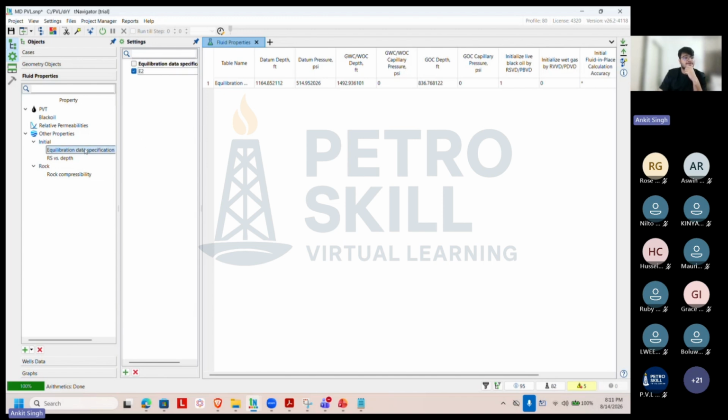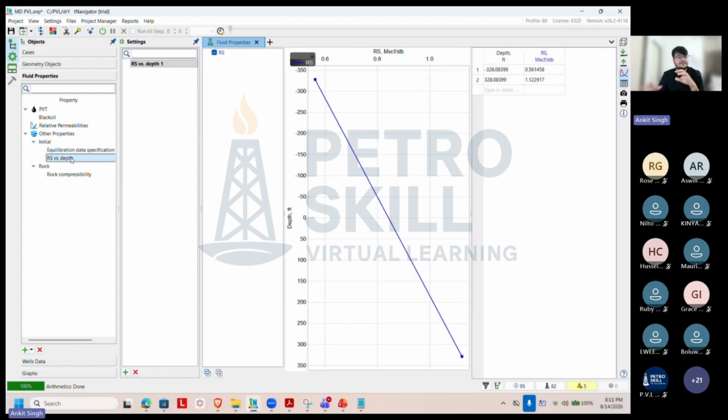Now that this is done, we go to defining the gas solubility versus depth. We have a gas zone as well, right? We have defined that there is a gas zone in our reservoir. We need to define how the gas is evolving on a depth basis. There are different values we can use. I have it all with me, I'll just enter that.